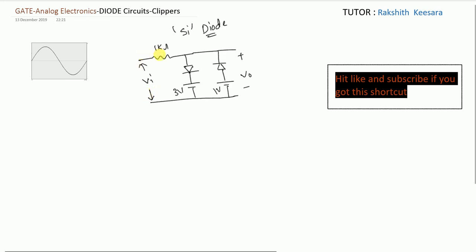So this is the next question, guys. In this question, instead of ideal diode, he given silicon diode. So we will see what will happen. Our first step is to open circuit the diodes. See, after open circuiting, since it is a silicon diode, our VA minus VC should be greater than 0.7. Since it is 3 volt here, if our input voltage is greater than 3.7, then only diode will turn on.